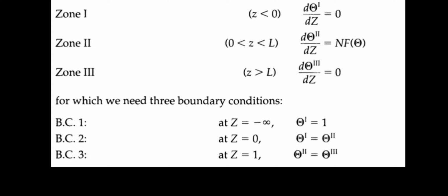And the third step is to solve the system of algebraic equations for the constants of integration. After applying all six boundary conditions, we will have a system of six simultaneous algebraic equations with six unknowns. Solving this system is often the most mathematically intensive part of the problem. The complexity of this step will depend on the form of the general solutions and the boundary conditions. Techniques such as substitution, elimination, or matrix methods can be used to find the values of these constants.